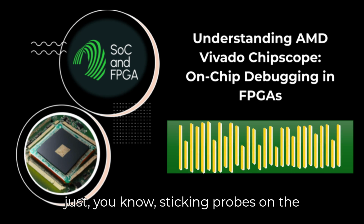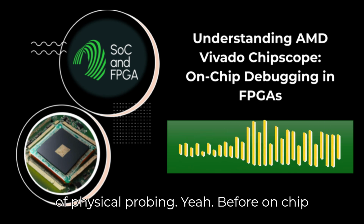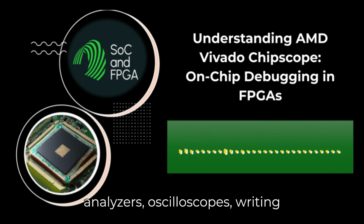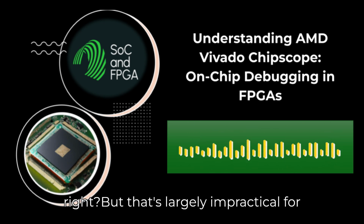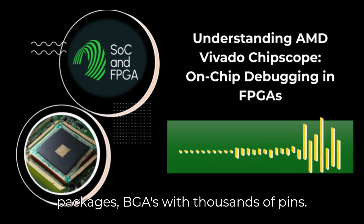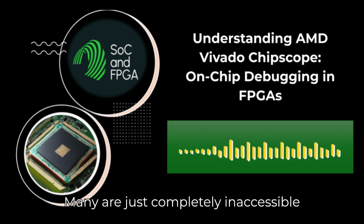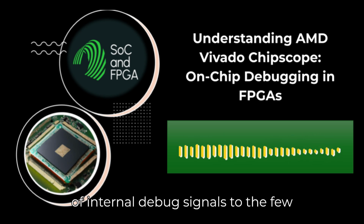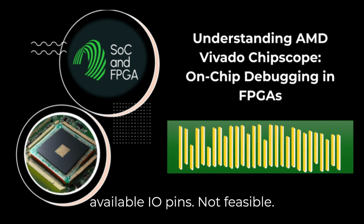Okay, so simulation has limits. What about just sticking probes on the board like the old days? The challenge of physical probing. Before on-chip debug, engineers used external logic analyzers, oscilloscopes, routing internal signals out to unused I/O pins. But that's largely impractical for modern devices, these high-performance FPGAs. They use ball grid array packages, BGAs, with thousands of pins. Many are just completely inaccessible under the chip. Good luck getting a probe on those. Exactly. Routing hundreds of internal debug signals to the few available I/O pins is not feasible.